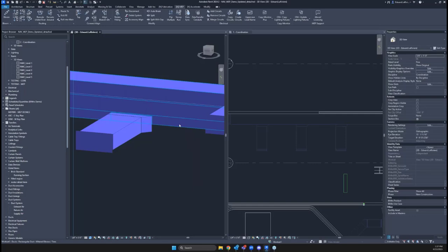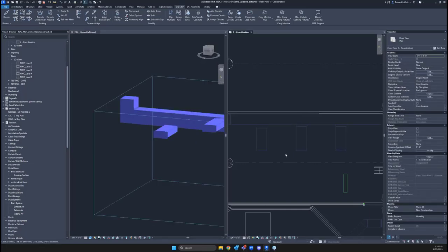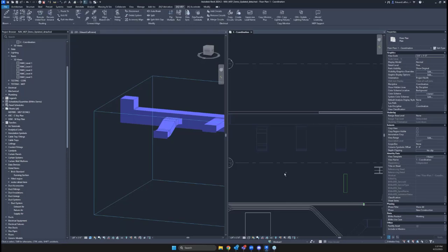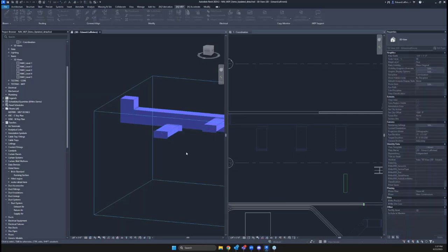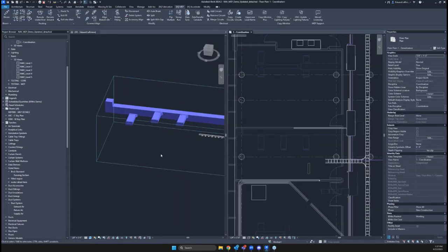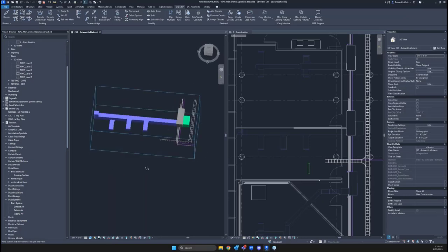We're fully connected now, actually connected together. Revit hates this. It's that tap off bottom of duct. And if you try to make this connection with trim extend, you get this nasty looking slope thing. So we all know in real life, they'll build a sloping boot, nice and easy to connect. Revit just doesn't like to show it. So tap is going to be our way to still show those connected, even if Revit doesn't really want to deal with it.